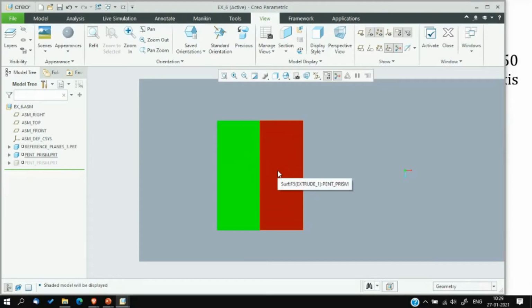But when one of the base edges was perpendicular to VP, or perpendicular to XY, that is in the previous case, the two rectangles were of different size. So in the previous case, in the view there were two rectangles, but both were of different size. But in this case, both the rectangles will be of the same size, that is in the top view.